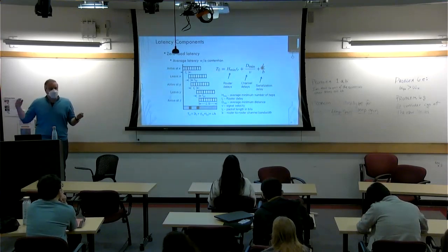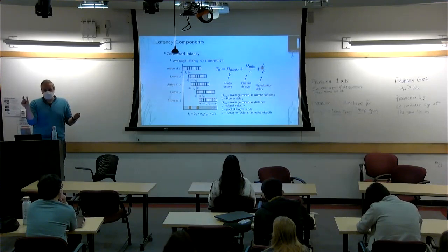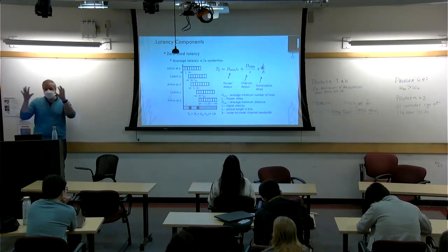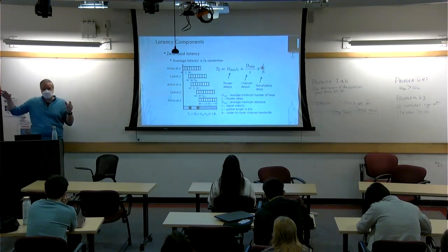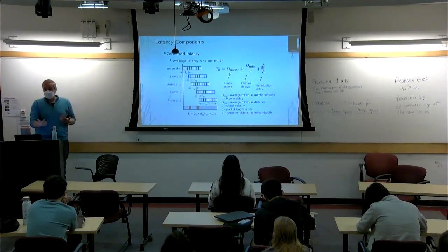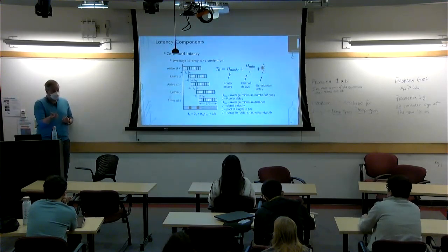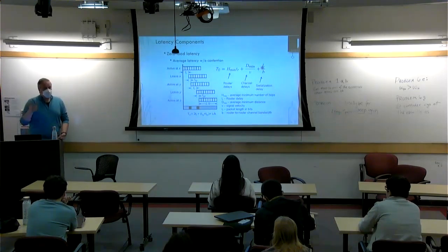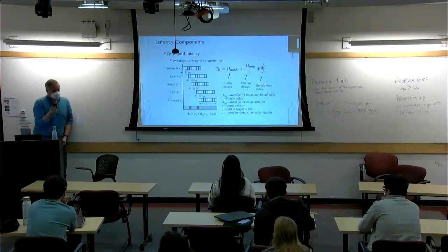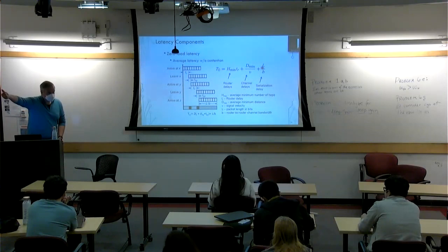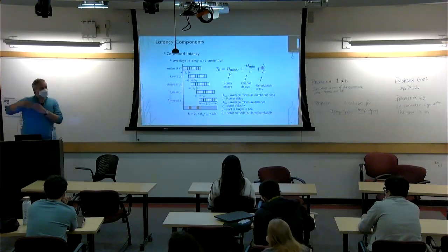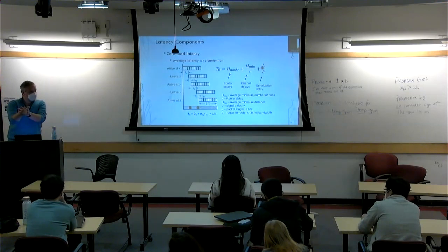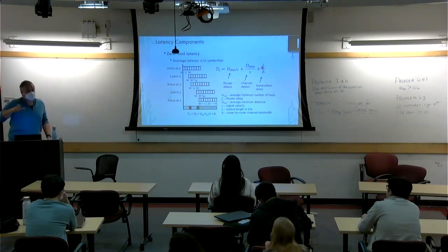And on the other end, there's nothing you can do on a smaller unit than 64 bits, because you need that information within the flit to advance. Then you have to wait for 64 bits, let's say divided by 8, which is our example channel width. You have to wait for 8 cycles for the whole thing to go through so you can use it. But if the flit was something you can use immediately to continue routing, then you only send 8 bits and everything else is pipelined behind it, but you keep going. So you don't pay that serialization delay right there.